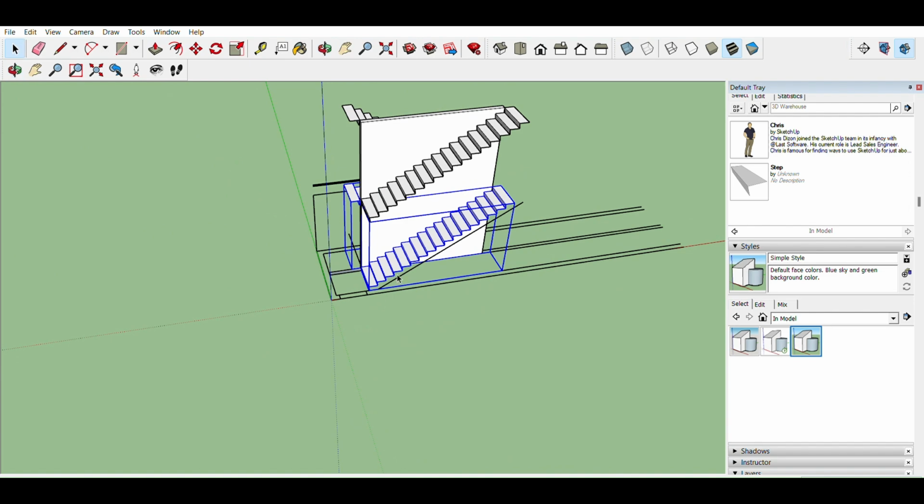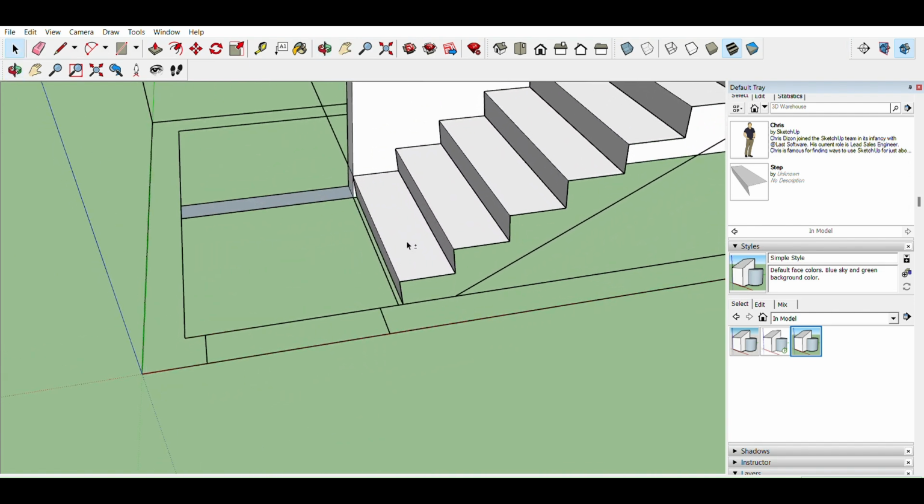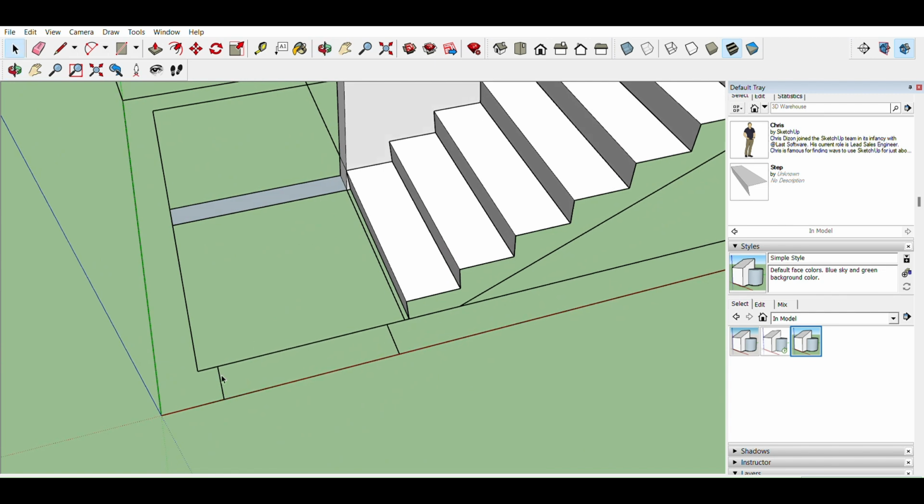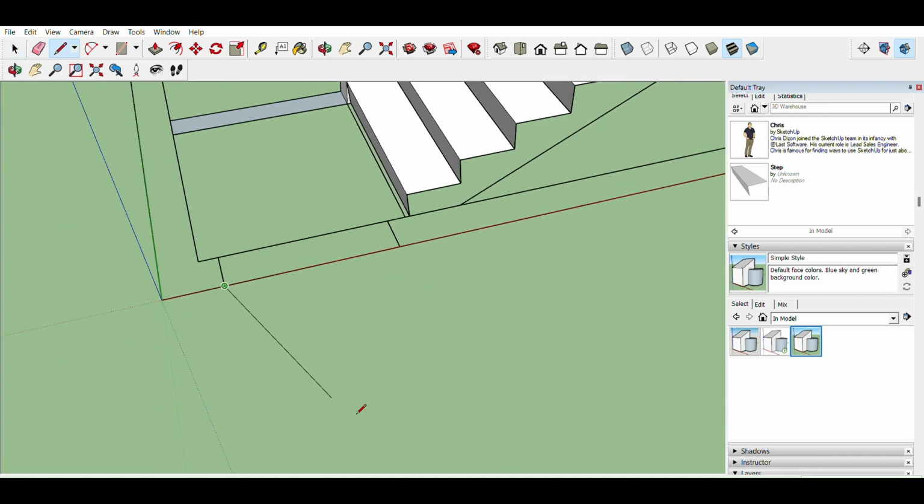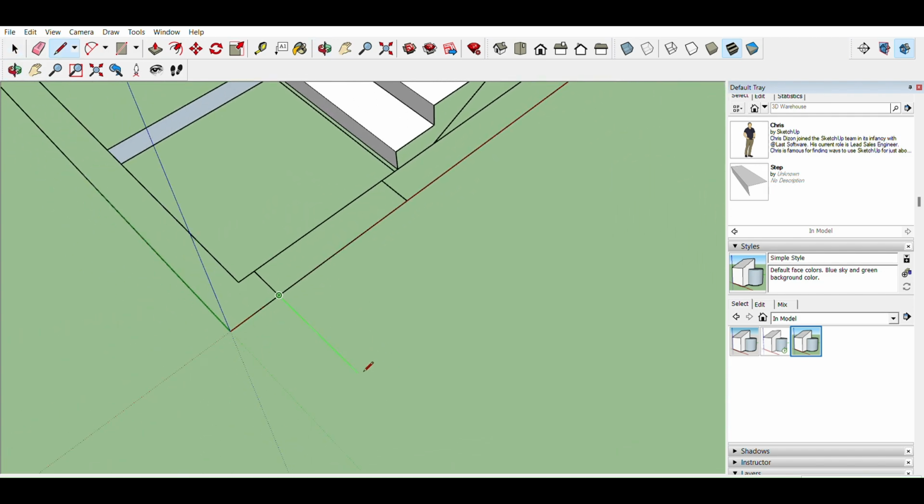And now I'm going to form the geometry for the remainder of the stair core. So what we have here is a 4-inch and then a 3-foot door that, in this case, swings out. So we'll go 3 feet. And generally speaking, for a door, you're looking at 1 3/4 inch.